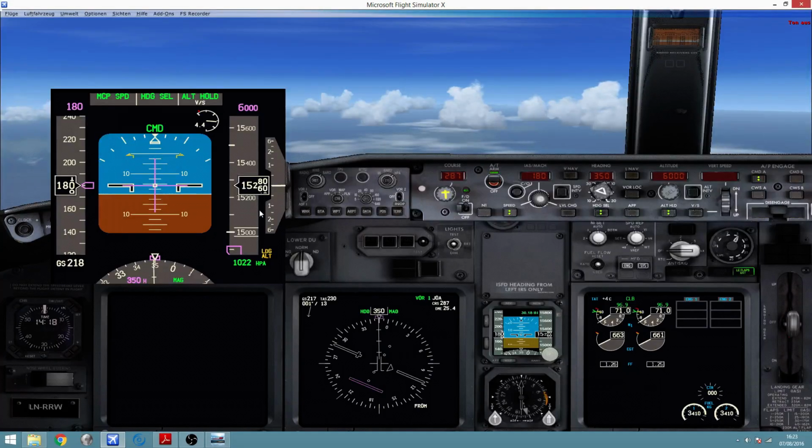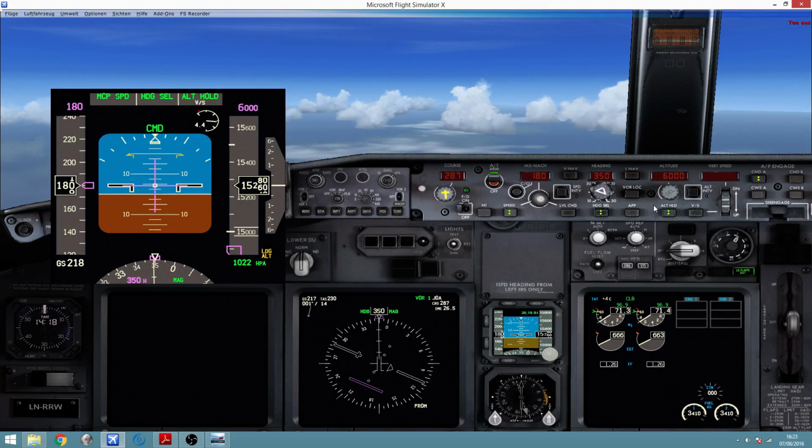Alright, because altitude is different from flight level. So this clearly shows how we can make mistakes if we don't change our reference pressure properly when we cross through the transition layer from QNH to QNE, or from QNE to QNH, as I just did. Now if I wanted to descend, I will talk later about what the commands are. I will just have to select the new altitude I want, or flight level, which is 6,000 feet.